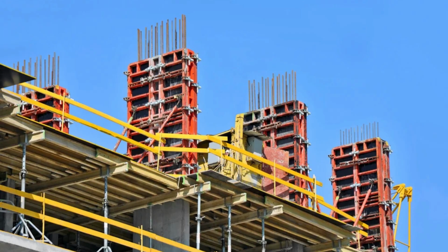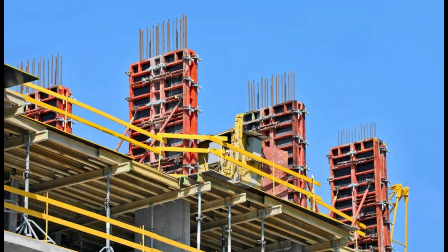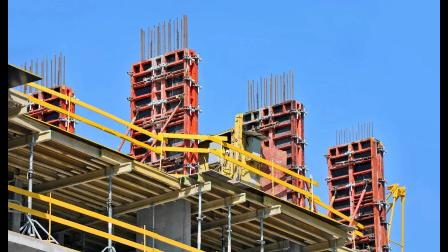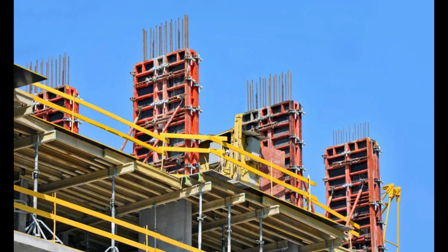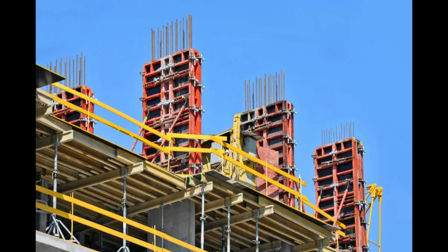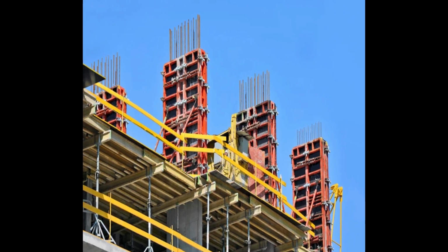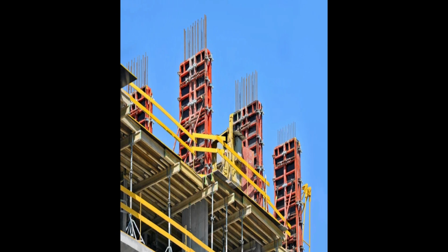Advantages of steel formwork: strong, durable, and longer life. It offers a smooth finish to the surface of the member. It is completely waterproof or moisture-proof and minimises the honeycombing effect. It can be reused more than 100 times. Steel formwork can be fixed and removed with greater ease.